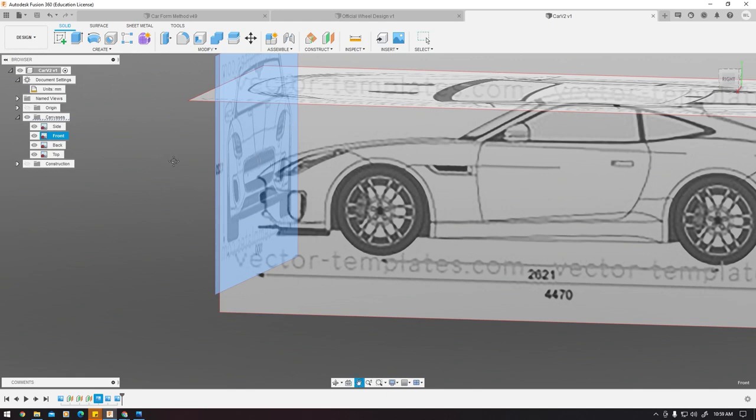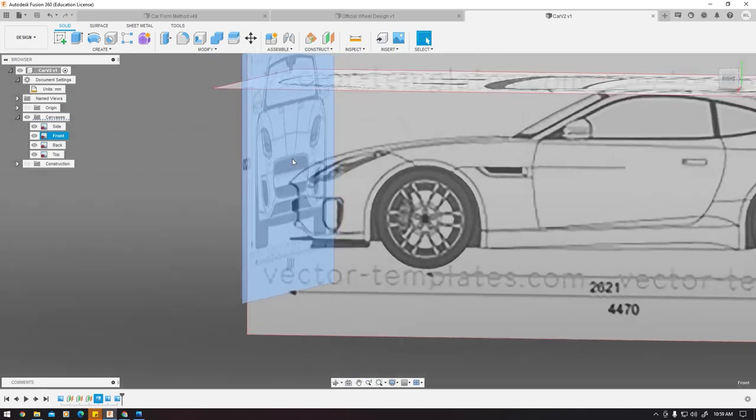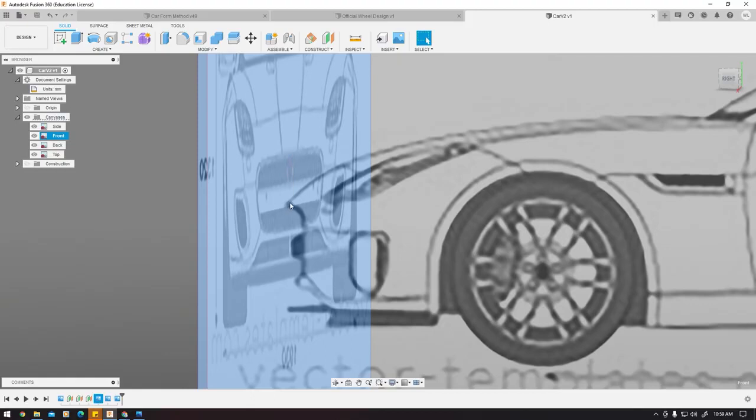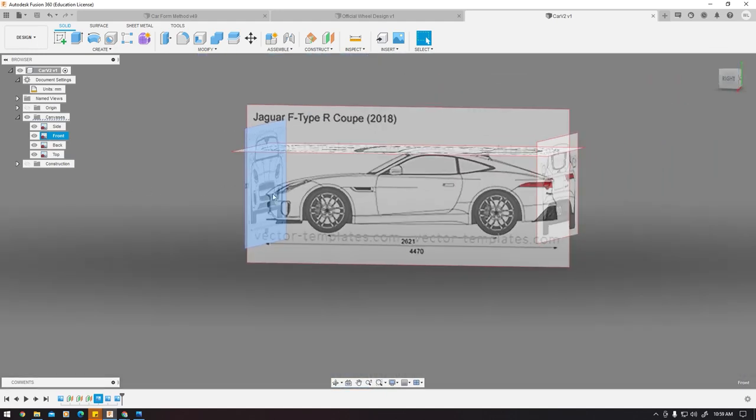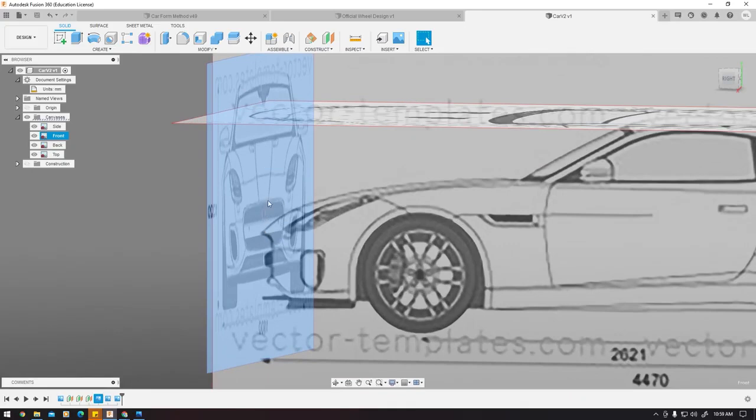Click on the front side, and you can see that this area is supposed to match with this front end of the car. To get it more exact, make sure you have orthographic views turned on for everything. So on the perspective view cube here, hit the down arrow and navigate to orthographic. Yours should be right now at perspective with ortho faces. Just click on orthographic, so it'll make everything orthographic. It'll make aligning these two easier.